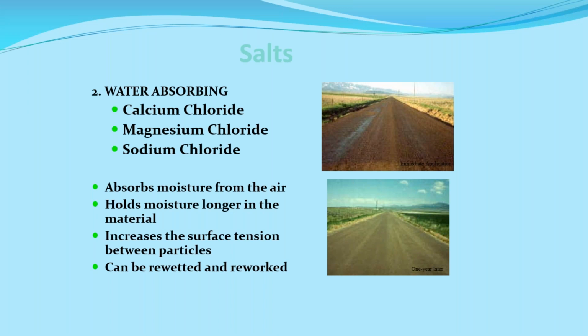The beauty about these salts is once you install them, they pretty much stay right there in the roadway. And you can rework that roadway with some water, and that chemical is still there. Generally, what I see most agencies do is if they're using one of these chemicals, they'll come in the fall of the year and rework the roadway. Then that following spring, they'll rework the roadway again, add a little more chemical, and then compact it, and then it'll be good for most of the summer. So that's the salts. You're able to pretty easily rework those types of products.